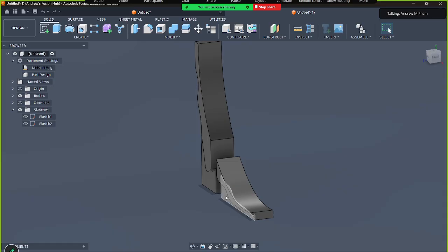But for another scenario where you might want these to be different sometimes, creating that offset plane and then extruding it afterwards, like the first person said, would probably be the way I would choose if they were susceptible to being different amounts of extrusion.